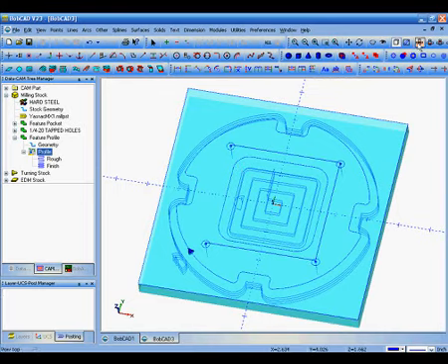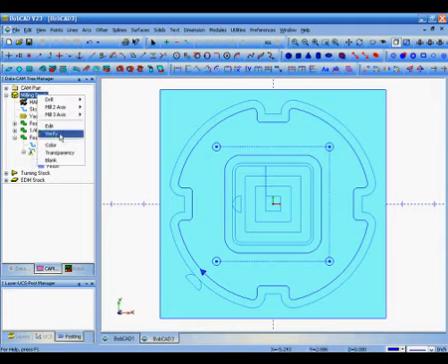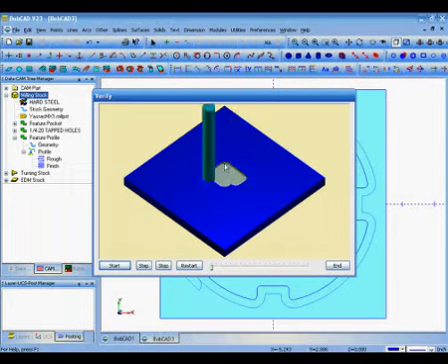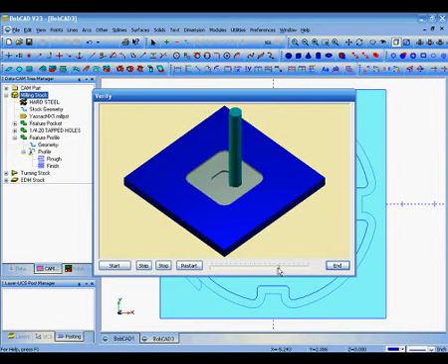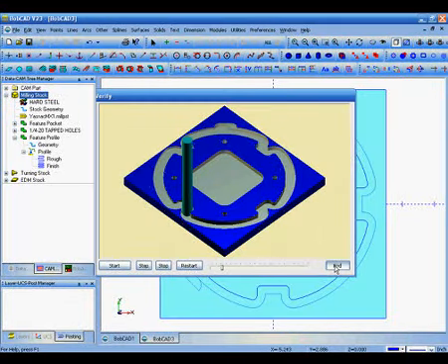Once we have all of our toolpaths on the screen, we're ready now to either post out the code or simulate the part. Now to simulate the part, we'd right-click Milling Stock, and then left-click Verify. And once the simulation comes up, we can click on Start, and then watch the cutter actually cut the part in the material that we had defined. The slide bar will either speed up or slow down the operations. Or we click on End to close.